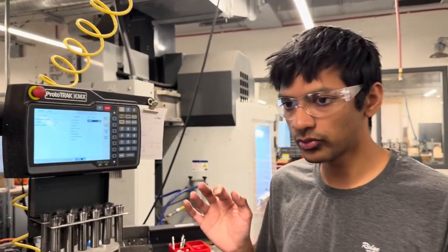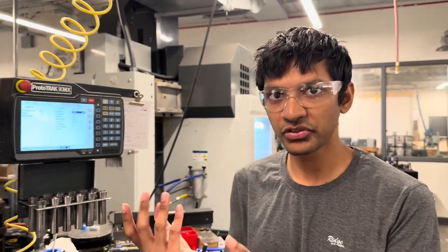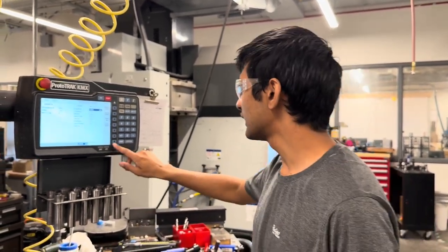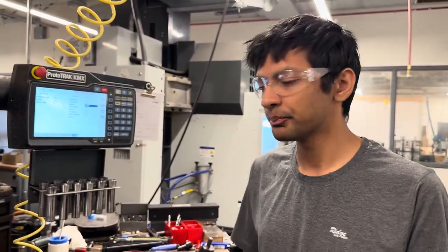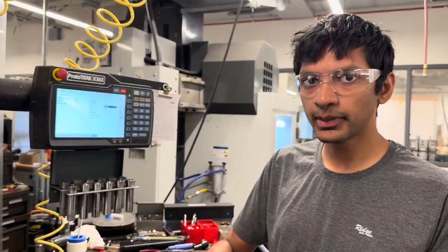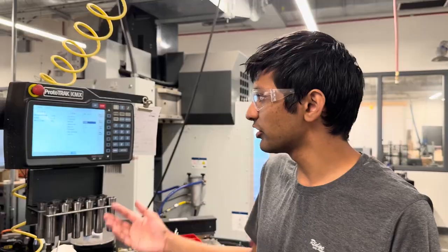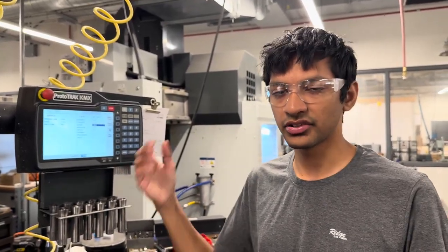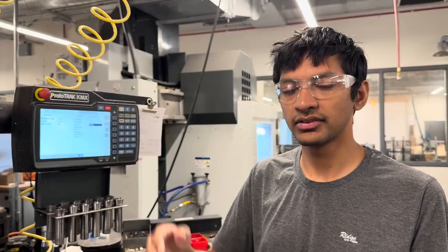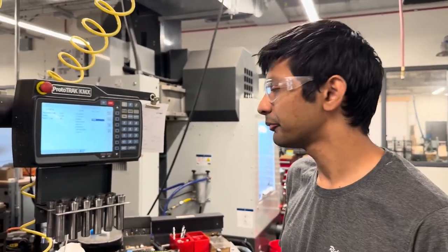Another use of this is for bearing fits. So just say you have a very precise bearing. What you do is you would set the radius a little bit under the OD of the bearing, like around 3 thou. Then you test fit the bearing to see if it goes in or not. It shouldn't go in. Then increase by like 1 thou or half a thou each time. Once you see it starts to go in, you can take it out and just hammer it in. And then you've got a pretty basic bearing fit.